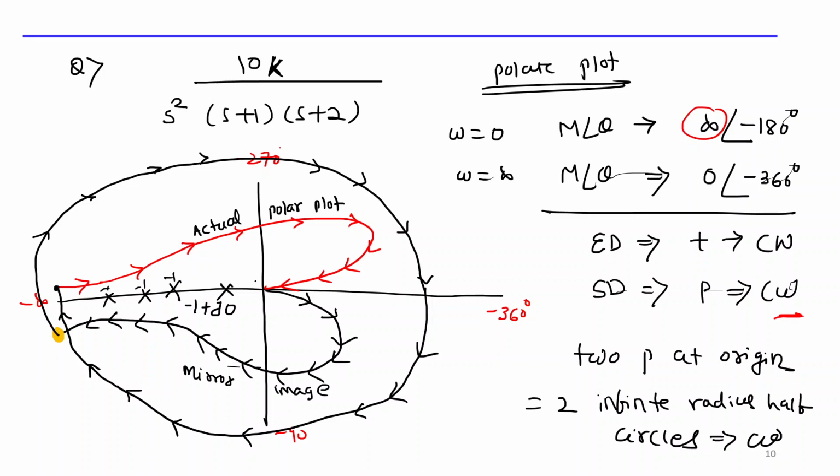Two encirclements. So the number of encirclements is 2. If you start from this one point, then you move like that, complete it, then move here another time, then you come back to the same point. So total encirclement is 2. So n equal to 2.